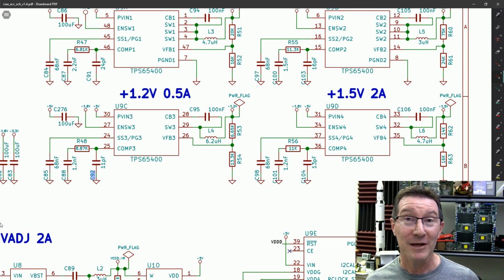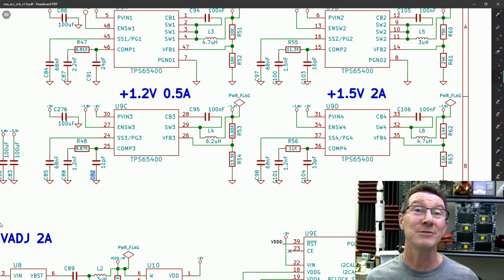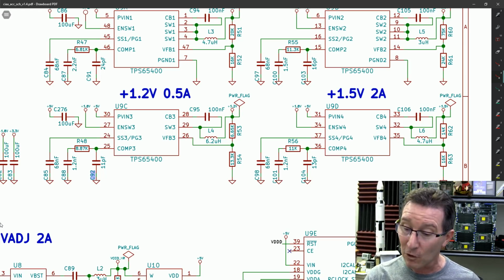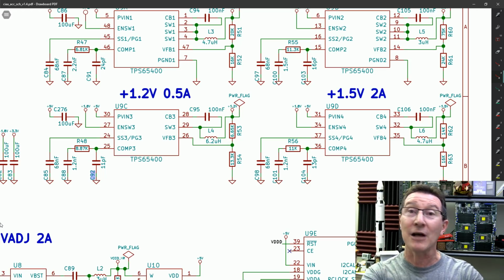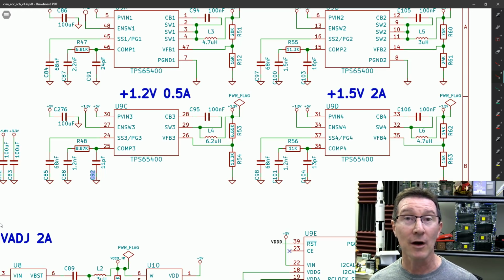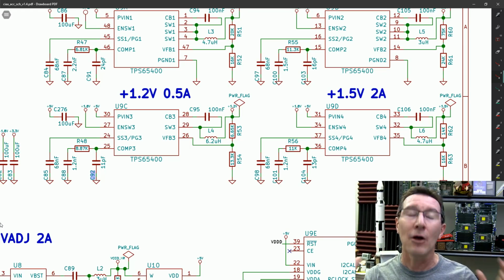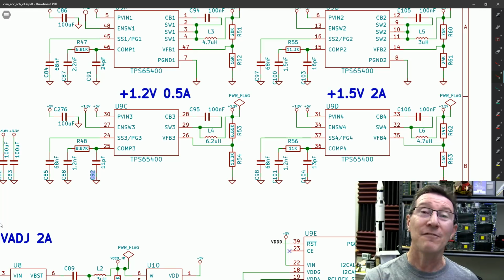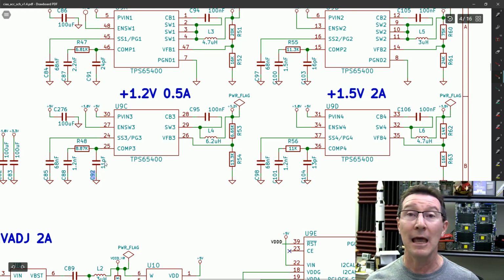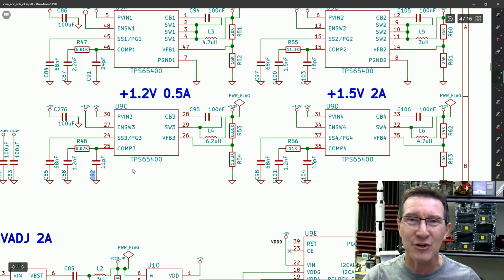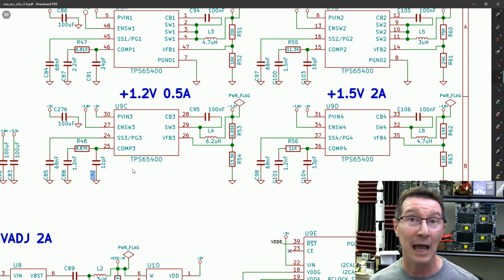Now, this is not uncommon in the industry. It's happened to me many times, where the purchasing officers, and yes, large corporations will have purchasing officers, their sole job is to source and buy all these parts for the latest production run of your widget that you're trying to actually produce. And they will often come to you and say, look, I cannot for the life of me get an 11 picofarad capacitor in an 0603 footprint. The whole world's out of them. I've scoured the grey market, cannot find them. Can we have a substitute?